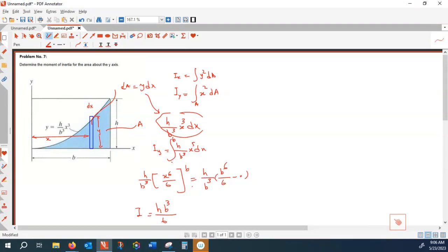Okay, when we are talking about internal stresses, this is not always the beam that we are talking about. Sometimes you are interested in stress in an average sense. In an average sense, generally speaking, it is either a cross-section subjected to a uniform axial load, compression or tension, in which case you calculate sigma, or a pin subjected to shear, or a lap joint subjected to shear. That is the force divided by the cross-sectional area tangent to the force.